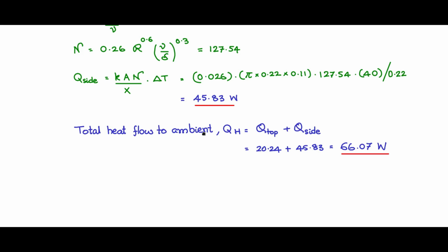This is the amount of heat that is coming from a combination of heat QC from the chamber and E from the Peltier electrical side. So let us look at the coefficient of performance now, which is QC by E, which is also equal to QH by E minus 1, which we worked out just earlier.